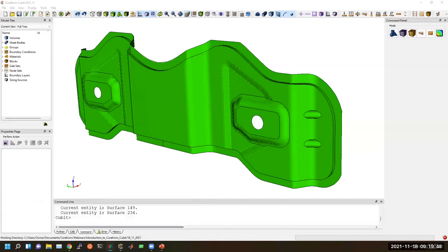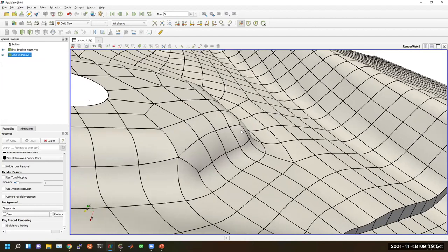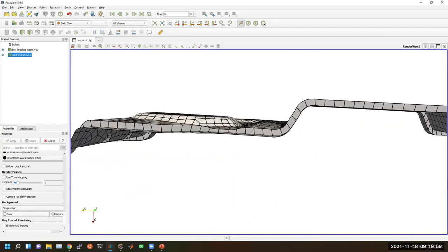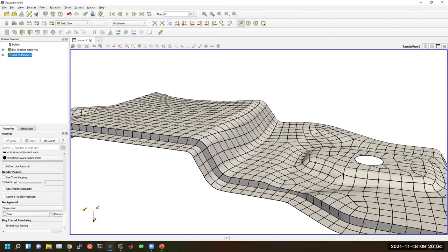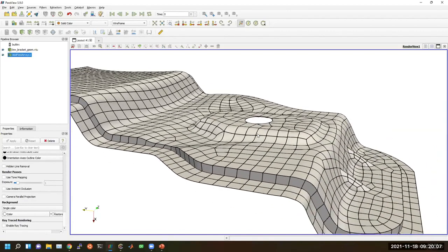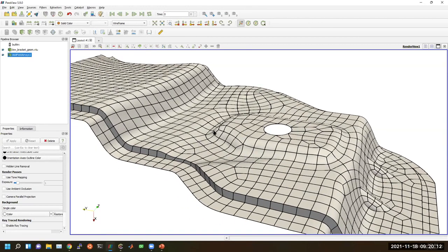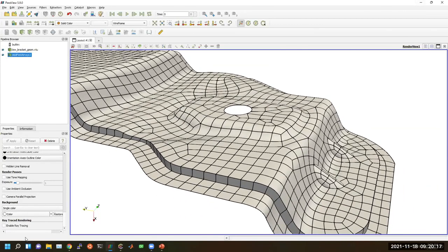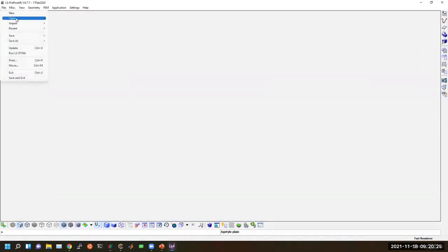Again, we can build the U-spline with a high order fit to that model geometry. And as you can see, the U-spline, with its smoothness and its higher order, allows us to get accurate fits to the geometry, even while defeaturing a lot of those geometric surfaces, or interfaces between those surfaces, away. And so you can actually run these models in ANSYS LS-DYNA, and I'll show you the results here.